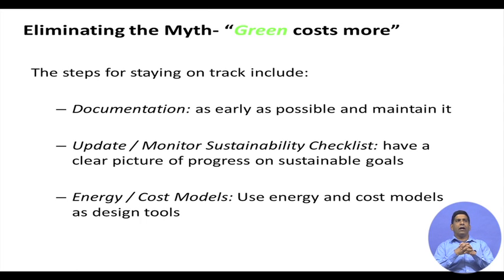We have to document the steps for staying on track. For any project, we have to document as early as possible and maintain it. Monitor the sustainability checklist, and have a clear picture of our sustainability goals. Do the energy model and the cost model, and use them as design tools to minimize the energy requirement and the cost. If you do these things properly, you don't end up paying more by going for a green building. As you saw from the previous two slides, in many cases a green or LEED certified building is actually less costly than a traditional building.